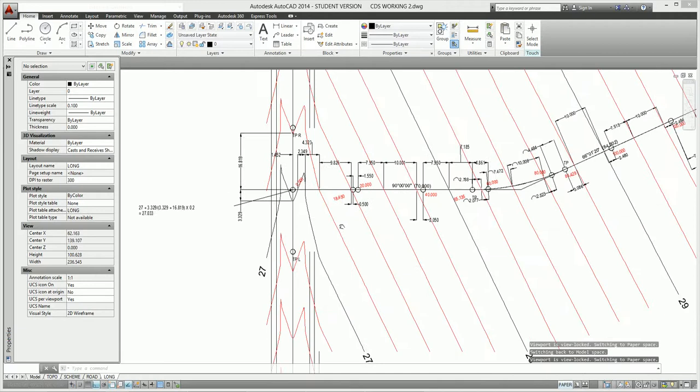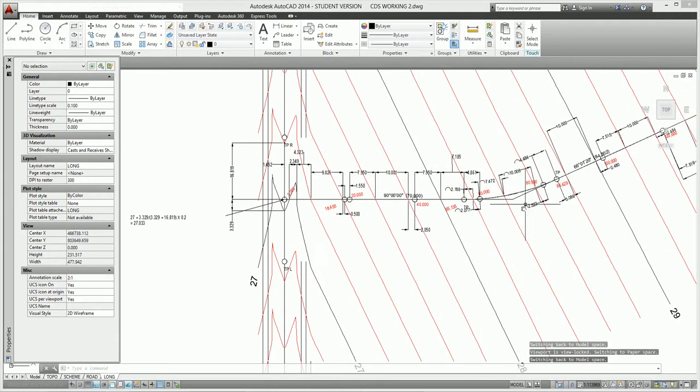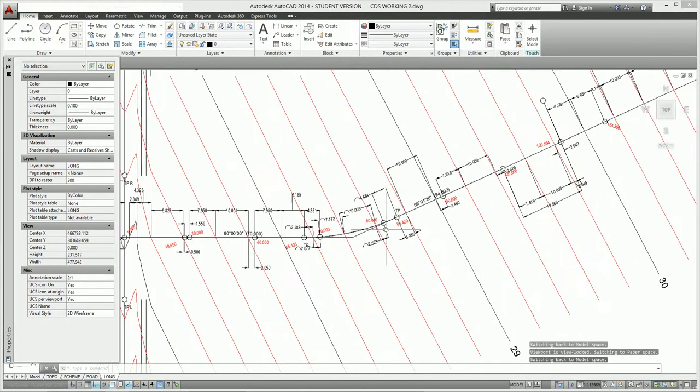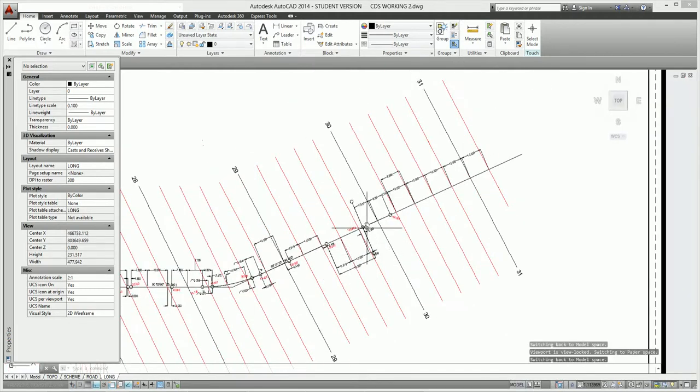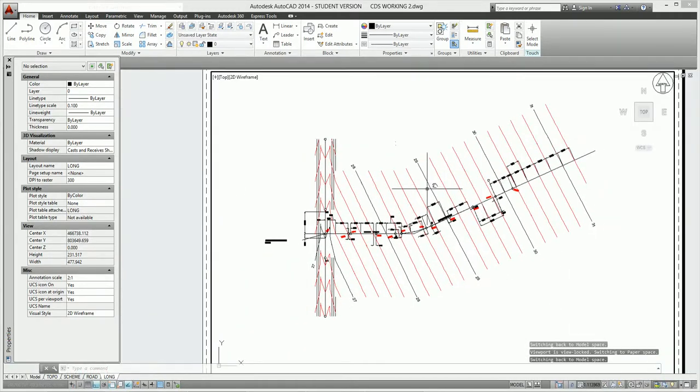And then there's all these little measurements. I measured the arcs and keyed in with the actual horizontal alignments and so on there, and what have you. So that is how I have managed to scale off and tabulate on an Excel spreadsheet the existing surface from which we're going to work on to do some more work on the vertical alignment.